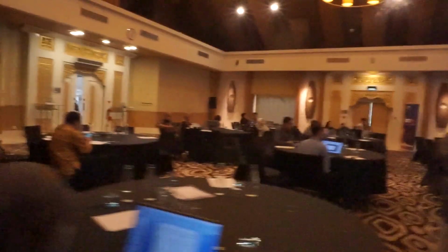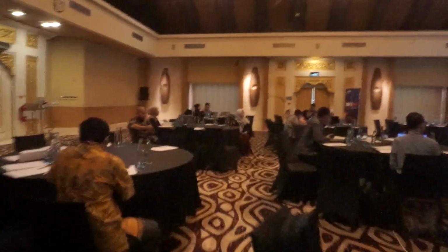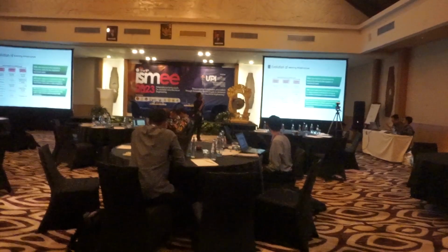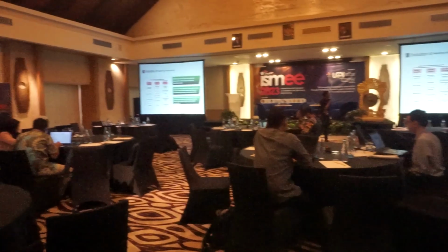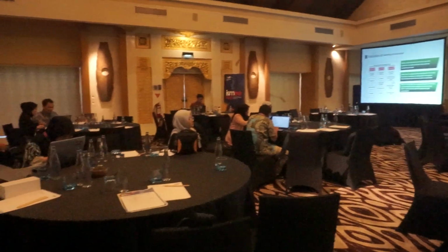And this is the evolution of metering infrastructure. The first one is MMR, or manual meter reading. The data collection is done manually by humans by reading the data displayed on mechanical meters. The second one is AMR, or automatic meter reading. Meter reading data is transmitted to the utility via wired or wireless communication through an intermediate node known as a data concentrator.